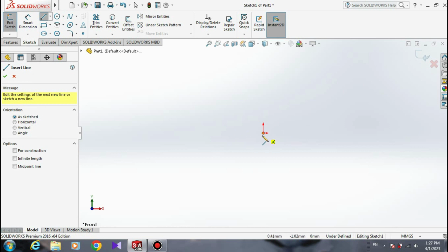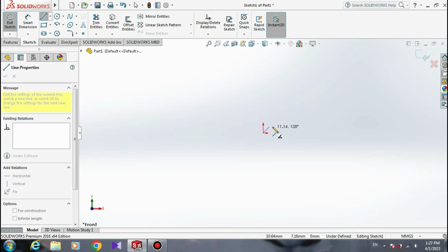When we want to create our sketch, we will only start with the origin point. This is our origin point. You can see a symbol will appear. If I get closer to the origin point, there is an orange point here. So I click on the origin point, and the line will appear. So I can extend the line as long as I want. You can see here I can extend it.